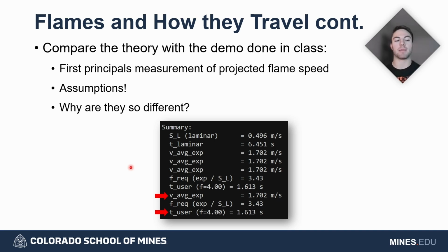If you look at the shape of the demonstration versus that chart I put up a few slides ago, the flame front looks significantly more like the turbulent flame than the laminar one. So that was the big assumption we made that probably threw these numbers way off. And once you know that, you could add in a fudge factor to say, hey, my data says this, but my code says this. If your factor is either linear or exponential, you can model that and give yourself an empirically derived model of the exact experiment, and then use that to predict other similar environments. And that can be a valid method, but for something like this, CFD would be the proper tool to use.